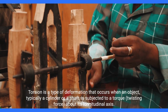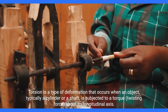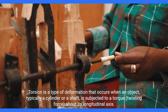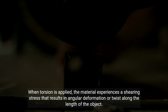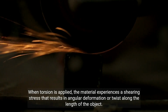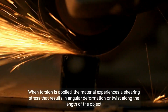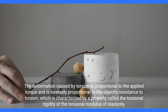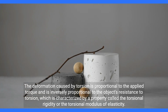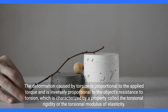Torsion is a type of deformation that occurs when an object, typically a cylinder or a shaft, is subjected to a torque, a twisting force, about its longitudinal axis. When torsion is applied, the material experiences a shearing stress that results in angular deformation or twist along the length of the object. The deformation caused by torsion is proportional to the applied torque and inversely proportional to the object's resistance to torsion, which is characterized by a property called the torsional rigidity or the torsional modulus of elasticity.